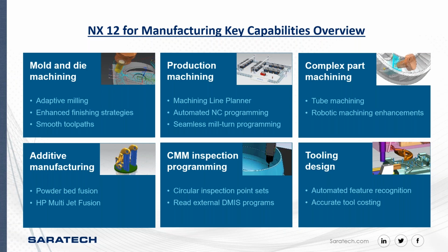So what they've given us is the ability to read in a G-code program or a DMIS program, give it a real life virtual setup, and then run that program with the tooling to validate it exactly as if Vericut were on board. So what they've done with our simulation module is giving us a much better module to compete with Vericut, and they've done a very good job at that. But going into the simulation module now from 11 to 12, it's a little bit confusing on what they've done and how it operates. So I'm going to go through a demo of that.